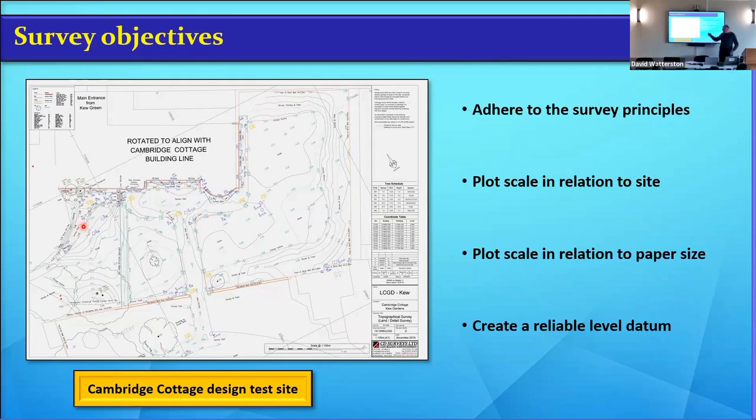So anyway, I pulled up the survey and it was a corner of a building that he was saying was 2 or 3 different. Now remember that we'd probably done the survey at 1:500, but possibly at 1:200. We might have done 1:100, but they're generally used to getting surveys at the scales that they have. So I went back to him and pulled the survey up. I said, actually, this survey's been produced at 1 to 200, 1 to 500, whatever it was. And you're saying the corner of this wall has 2 or 3 points in it, and they vary by 2 or 3 millimeters.